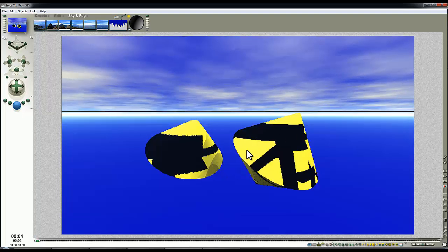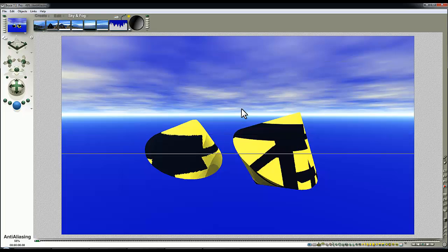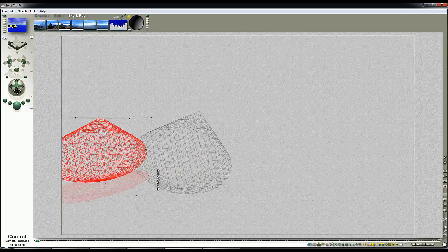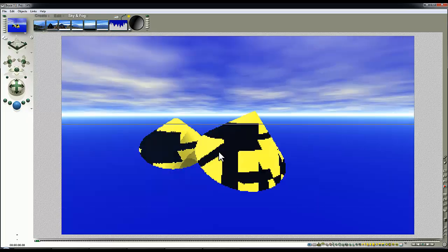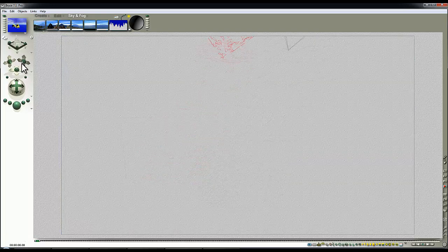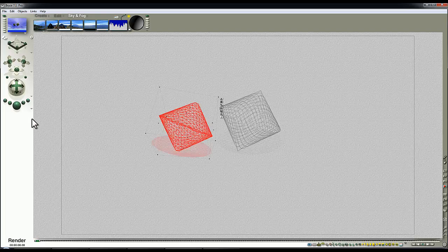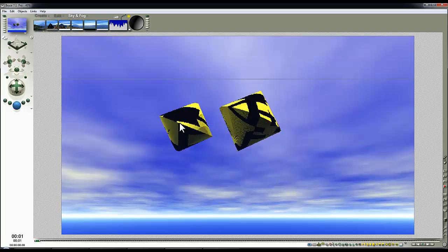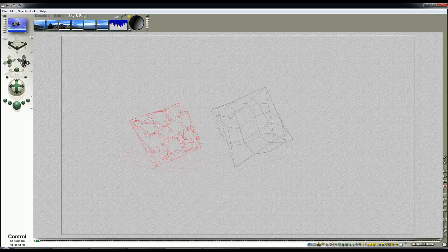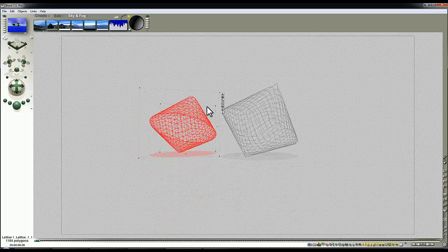Now there's a bit of a problem here because it's brought in an image which you can see relates to the pattern that's on the original, but there's some scaling issue occurring there, and so obviously something's gone wrong in the way it's rendered its map. I've done a few tests on this and you don't really need to see me go through that. You'll notice also there's a disjoint there, it's not joining over the edge as the original one did. And what's happening is when it renders the maps, it's rendering this as if the clip zone wasn't there.